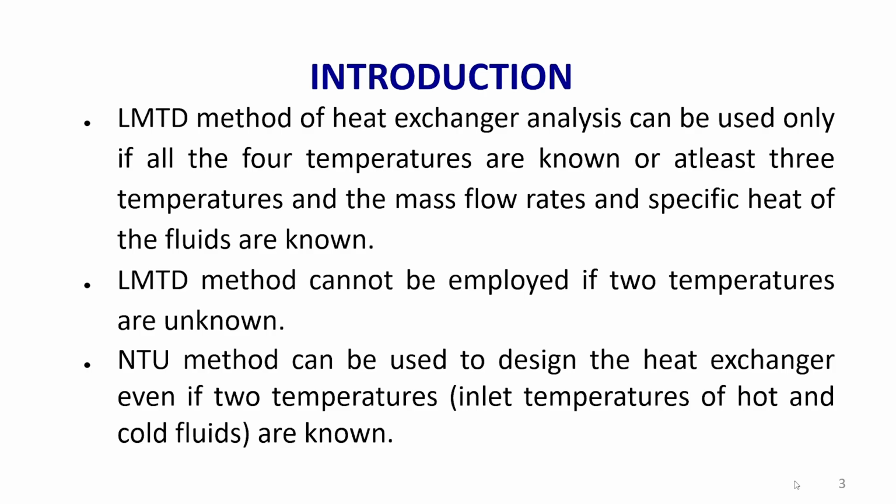So, in case we have three temperatures given, hot fluid inlet and outlet are given, and for the cold fluid any one, mostly the inlet temperature, will be given. That means we can find the rate of heat flow, that is how much heat is lost by the hot fluid, or if you know both temperatures of the cold fluid, we can find how much heat is gained by the cold fluid, provided we know the mass flow rate.